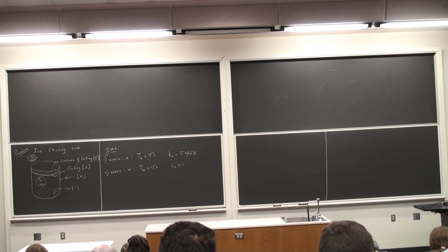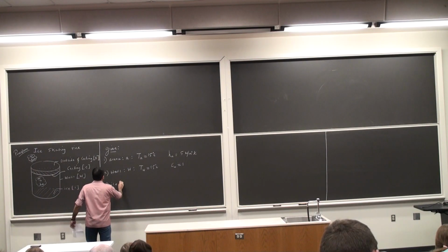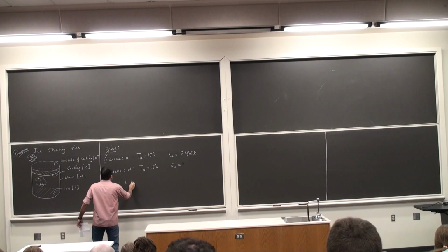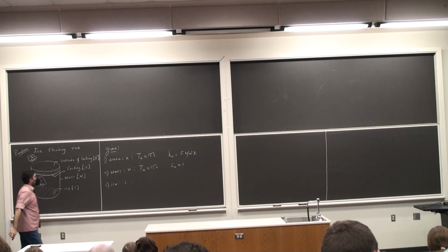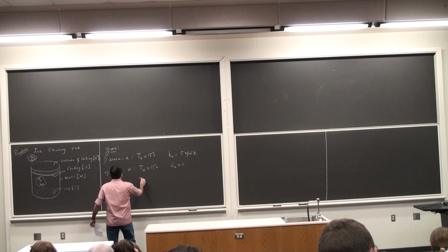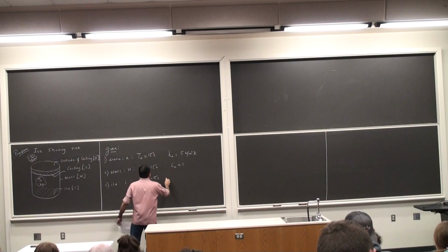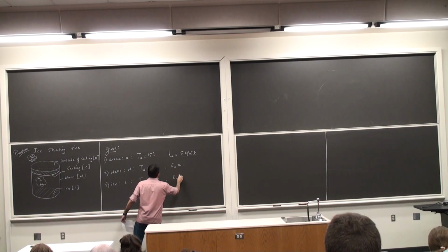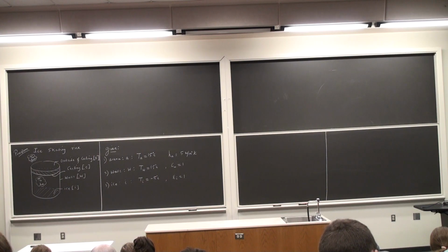Then for the ice, which is the bottom, little i, T_i is given to us as minus 5 degrees Celsius. And epsilon i, we have to treat the ice surface as having an emissivity of 1 as well. Then ambient conditions and then ceiling conditions.